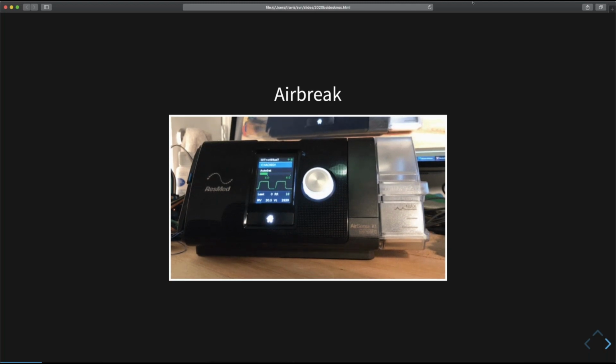And more recently, Trammell Hudson has been playing around with this thing, which is a CPAP machine that he's attempting to firmware patch into being a respirator. In all of these, you need to begin by understanding the architecture that you're working with. Then you need to dump a firmware image, load the firmware image into a reverse engineering tool, and then read it and annotate it until you can understand what it does.